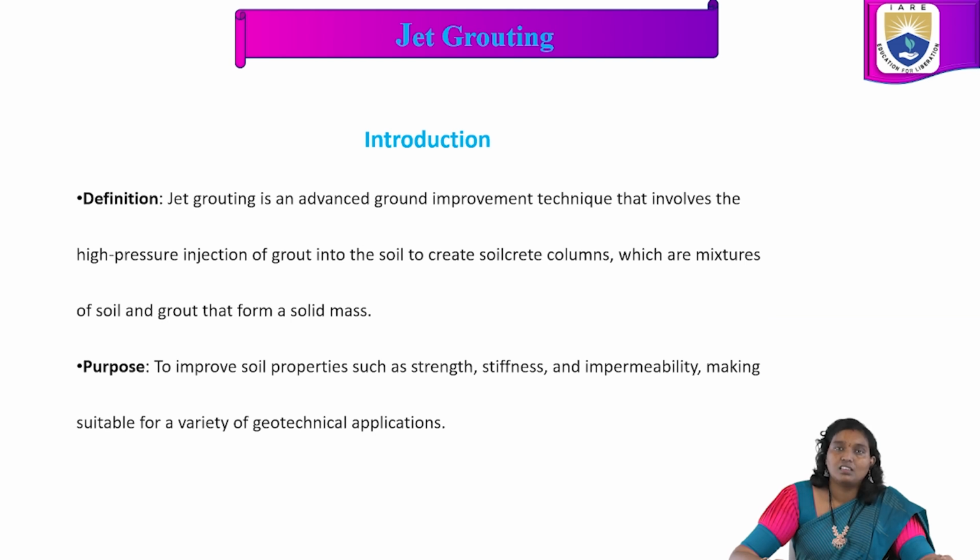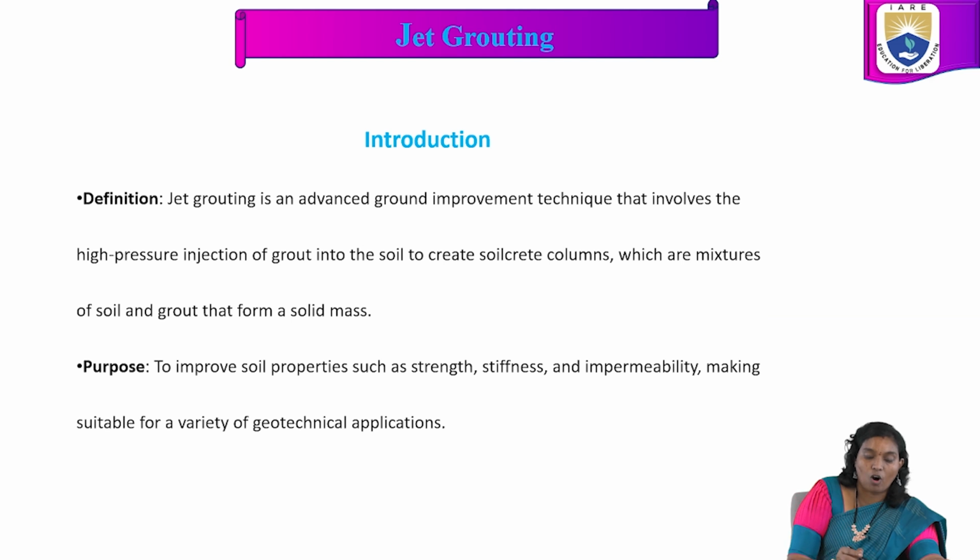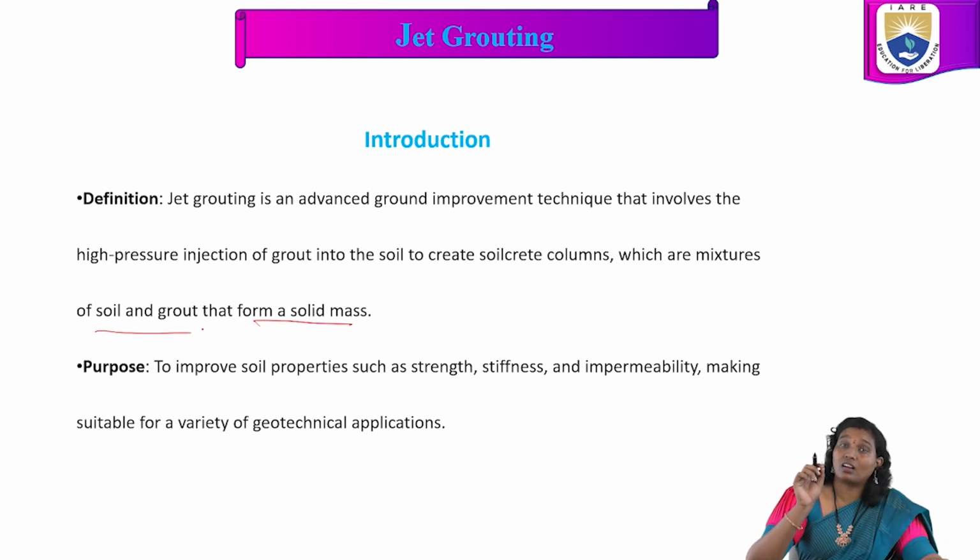Jet grouting is an advanced ground improvement technique that involves the high pressure injection of grout into the soil to create soilcrete columns, which are mixtures of soil and grout that form a solid mass. So, we know about grouting.